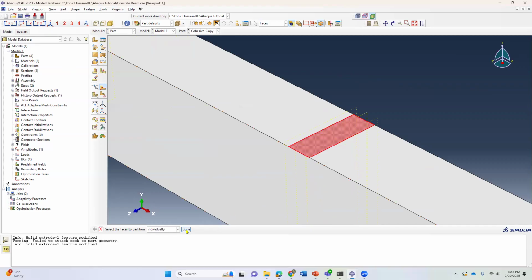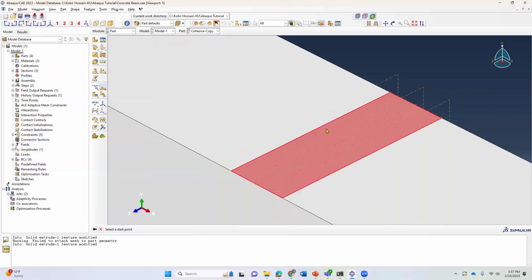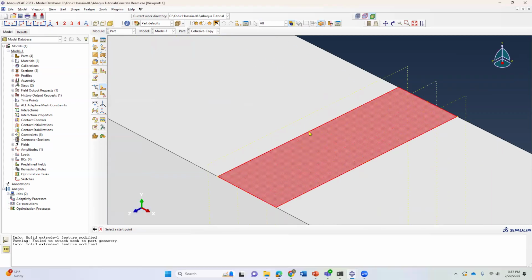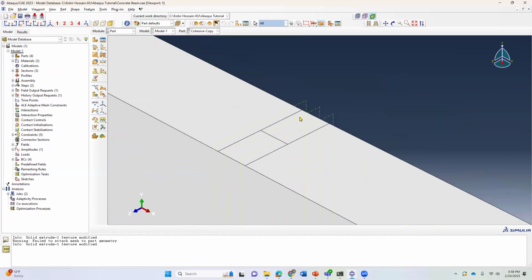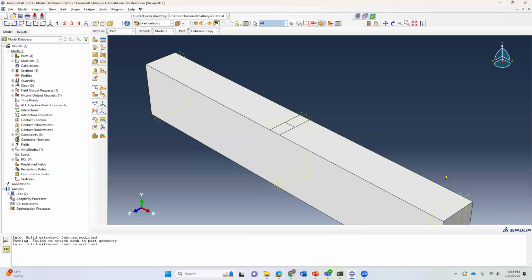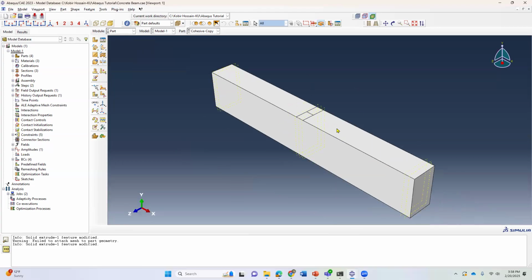So support, select this surface, starting point. I can see the yellow point. I don't know if you will be able to see it, but you can see the midpoints of this line and this line. So by selecting that, we can do it. We could have created a parallel datum plane like the previous ones. But since it will have these planes visible, and we have the 2-point option, that's better.